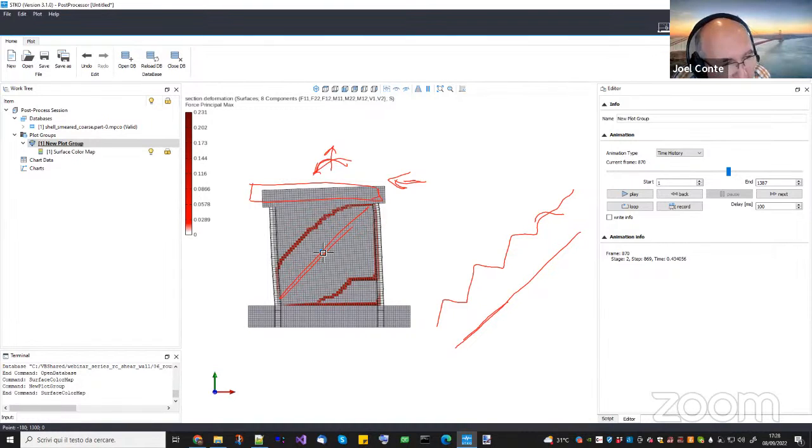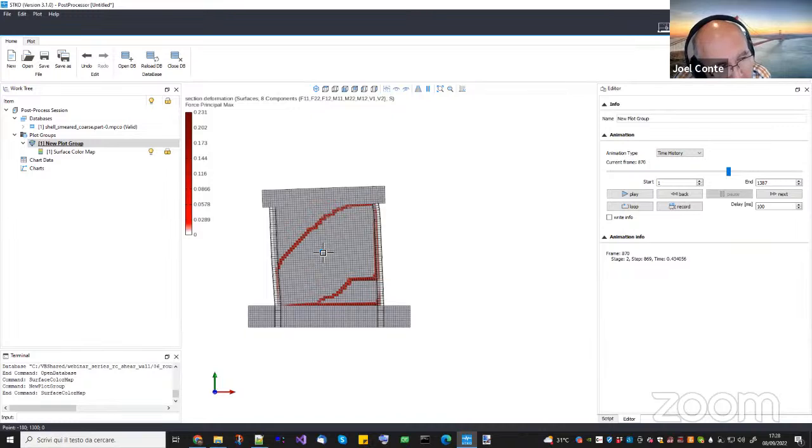Massimo, another question. Can you comment on the shell modeling approach? I mean, from a high level, the beam truss model is more physics based, more fundamental, so to speak. Now, what about the beam truss model? Everything is uniaxial, so the stress strain constitutive models are uniaxial. It's very easy when you are uniaxial to put many types of phenomena in the constitutive model.